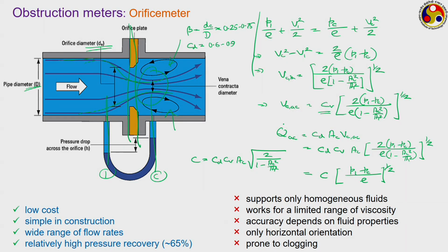While everything looks quite good as long as you are sticking to a general fluid and with moderate level of velocities, the biggest challenge is to know the position of this vena contracta, because that is strongly dependent upon the channel configuration, dependent on the fluid itself, and even for a given fluid on the flow velocities.